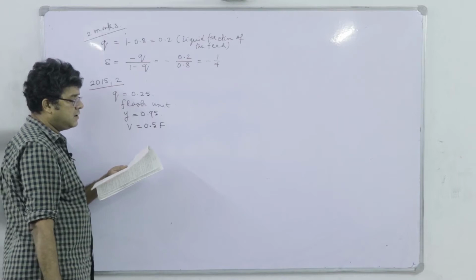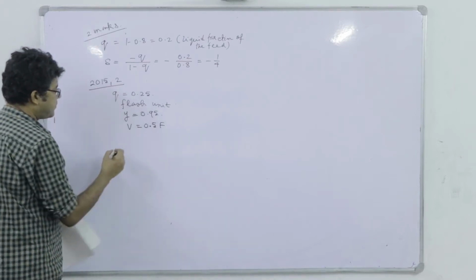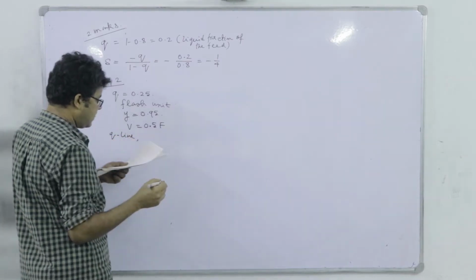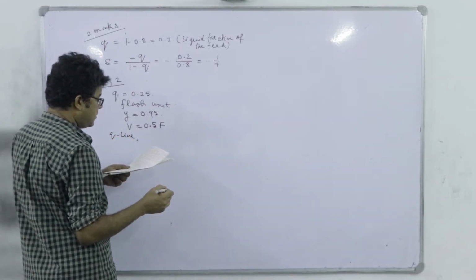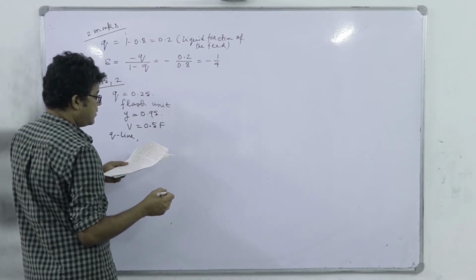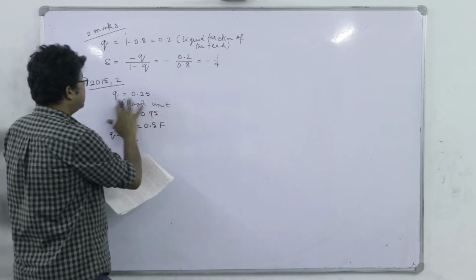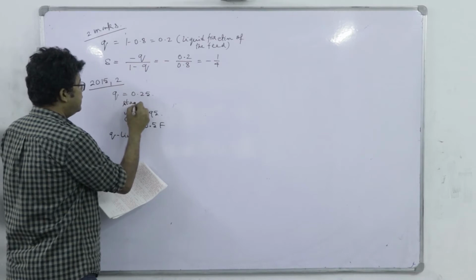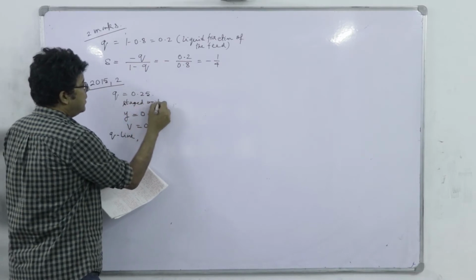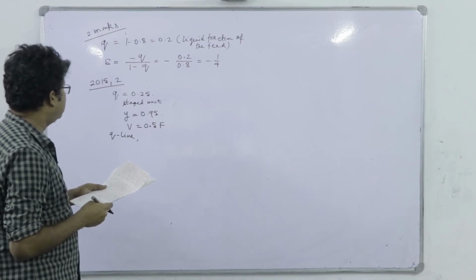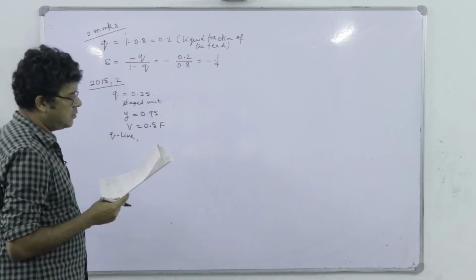The q line intersects the operating line. In a single stage, no? It is a staged unit. That is why I was confused when it is stated McCabe-Thiele. So, it is a staged unit. q is equal to 0.25.